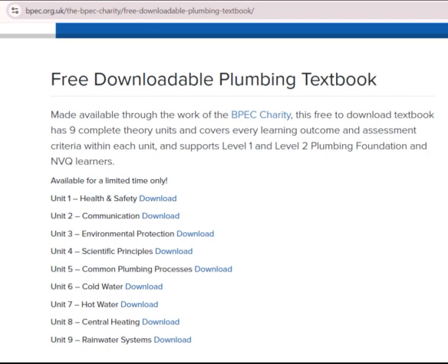Typical alloys in the plumbing industry are listed below. Brass, a mixture of copper and zinc. Used extensively for fittings and components. It corrodes when in the presence of hard water, as copper and zinc are dissimilar metals at opposite ends of the electro-chemical series of metals. Electrolytic corrosion occurs where the noble metal copper destroys the weaker sacrificial metal zinc. For this reason, low zinc content brass is made, which is dezincification resistant.